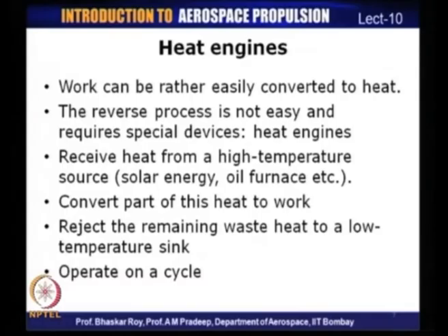You don't really need a heat engine to convert work into heat, but if you have to generate work from a certain heat, you need devices known as heat engines. Heat engines basically receive heat from a high temperature source, which could be solar energy or an oil furnace, and then convert part of this heat into work and reject the remaining waste heat to a low temperature sink, which could be the atmosphere or a lake or a condenser. Therefore, heat engines always operate in a cycle.